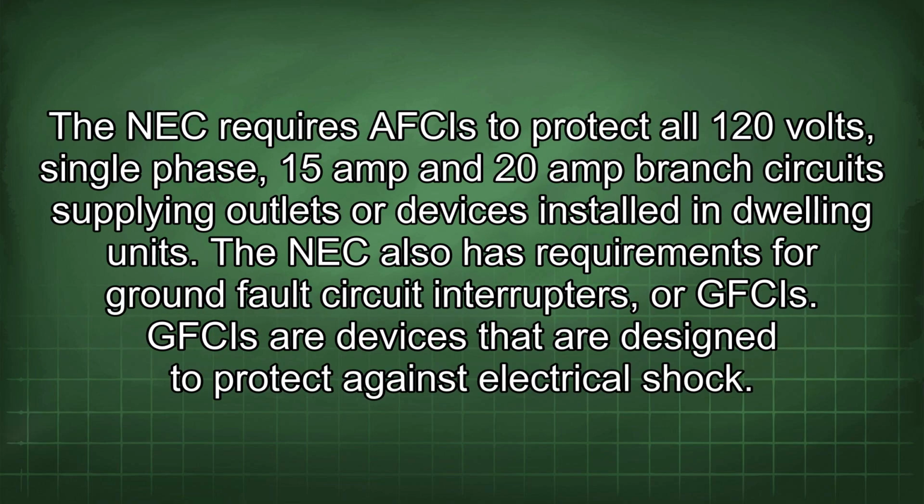The NEC requires an AFCI to protect all 120 volt, single-phase, 15 amp and 20 amp branch circuits supplying outlets or devices installed in dwelling units.